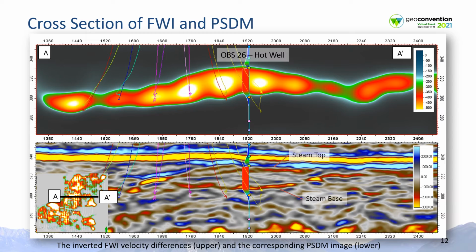In this east-west cross-section, we show how the temperature logs in the vertical observation wells provide another set of control data. The horizontal well sticks are shown here projected onto the cross-section. The velocity difference color legend was adjusted to correspond with steam temperature in the observation wells.